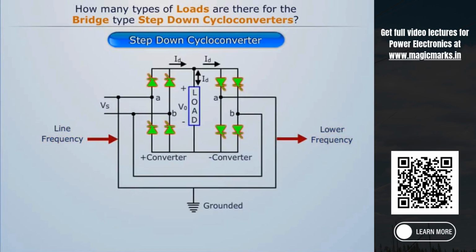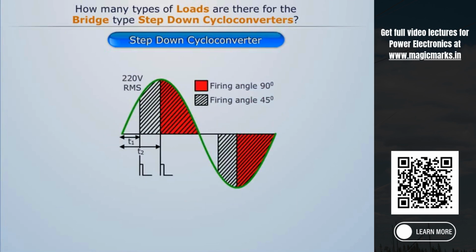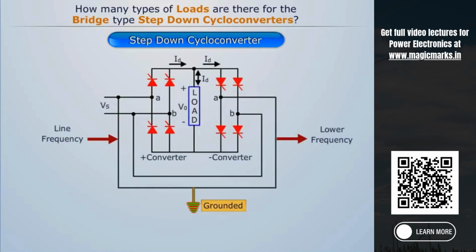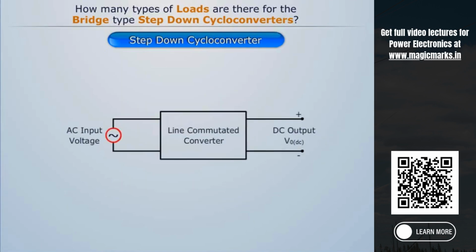The two bridge-type controlled rectifiers are connected in anti-parallel direction via 4 ideal switches. The time period of the ideal switches controls the output frequency, and the voltage can be varied by the firing angle of the SCRs. By using 4 switches, the grounds of both the converters are isolated. We've discussed earlier that converters require natural commutation, which is provided by the AC supply.